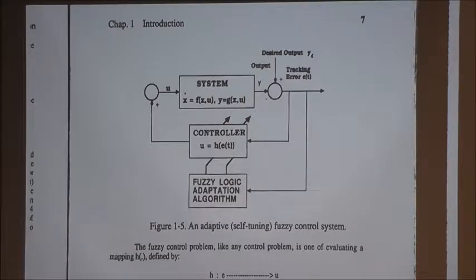Okay, and it's also possible that the robot may have a change in its dynamics. For example, if a mobile robot has a big load on it, and it clears part of it and moves on, that robot has changed its mass, the center of gravity has changed, the mathematical model has changed.